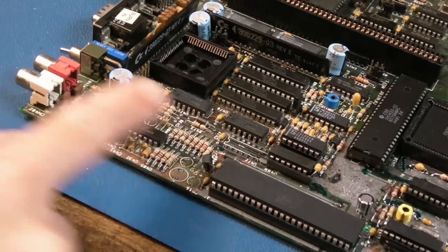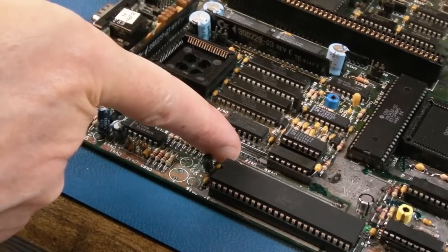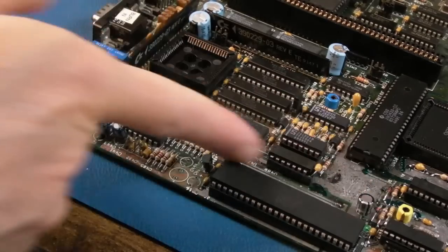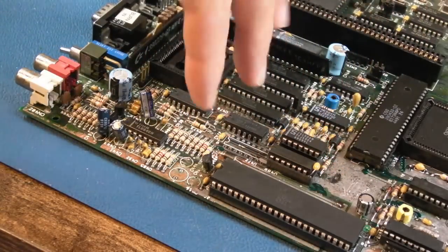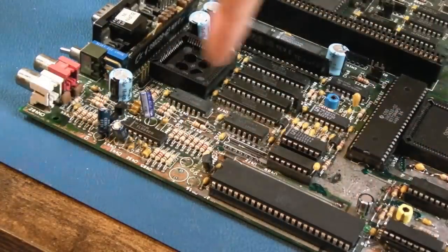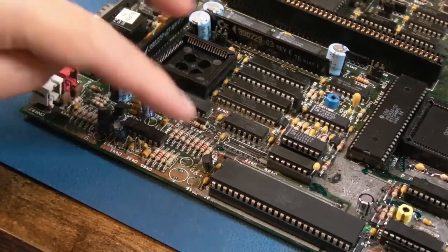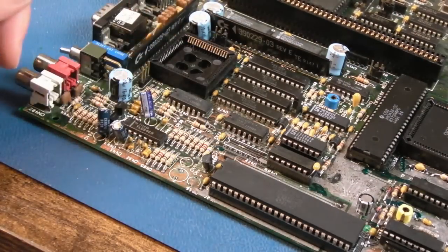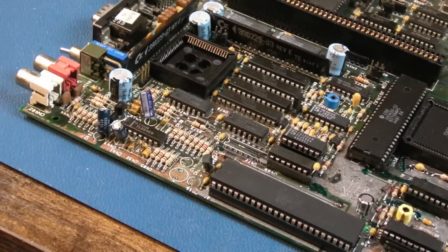Yeah, the audio thing here, this channel, that wouldn't be broken if it wasn't for the trace that was right here. It's anything that's in direct sight of the battery, because it goes under things and gets blocked by various things, so inevitably it sort of stops after a certain radius, and then you just get a tiny layer of it that manages to get onto the surface of everything further afield. But yeah, you just lose the solder mask. The traces seem to be okay.